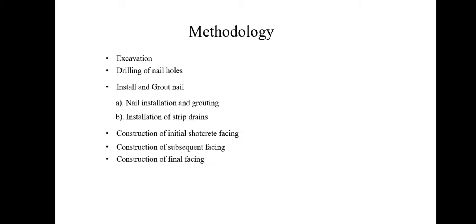So next is methodology. Methodology includes excavation, drilling of the nail hole, and then installation and grouting of the nail, which contains two steps: nail installation and grouting. Then installation of strip drain, construction of initial shotcrete facing, construction of subsequent facing, and construction of final facing.